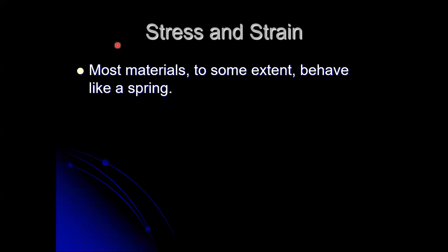If each inch grows by 5 thousandths of an inch, you're going to need lots of inches put together before you'll be able to put a tape measure on that and actually measure it. But strain and stress are connected together. Stress is the internal equivalent of force. Strain is the internal equivalent of deformation, of change in length, of elongation. And stresses cause strains to occur, just like forces cause elongation to occur.